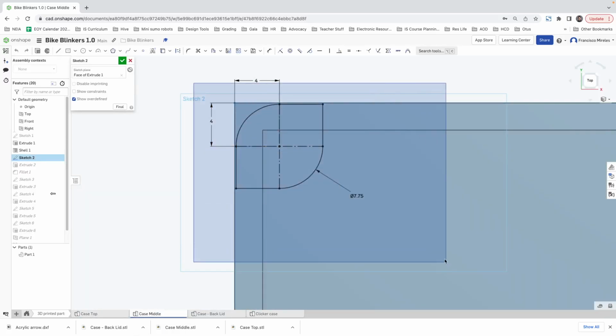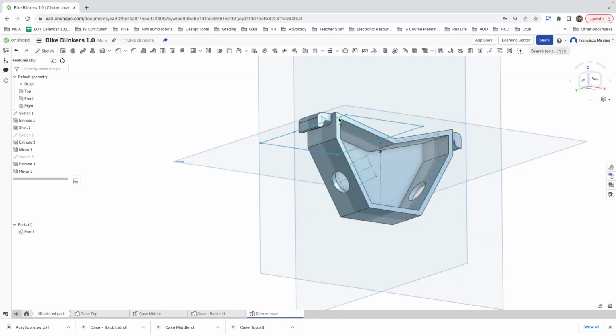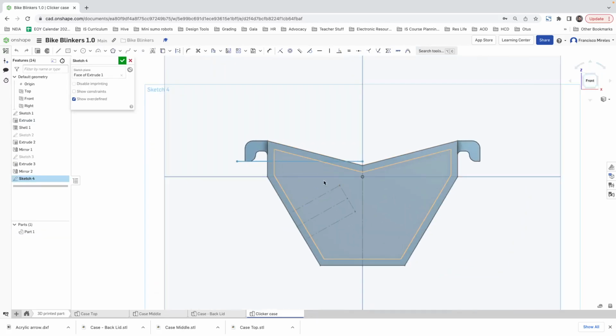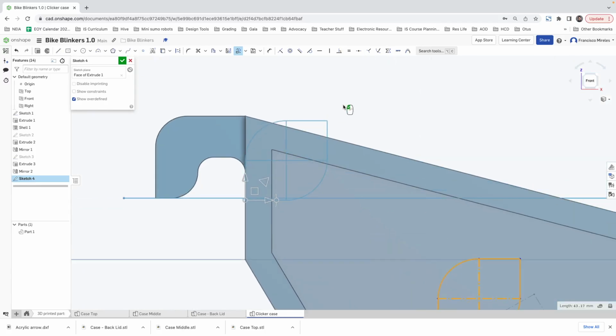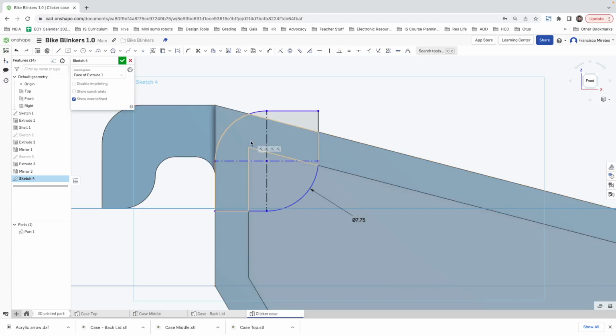I think I can just do this, Command C, then go to this face, new sketch, and then I can, oh, but you know what? The only issue is that I don't have a 90-degree angle. I mean, it still might help me give me just a reference. So what I can do is I can do distance from here to here, do a 4.